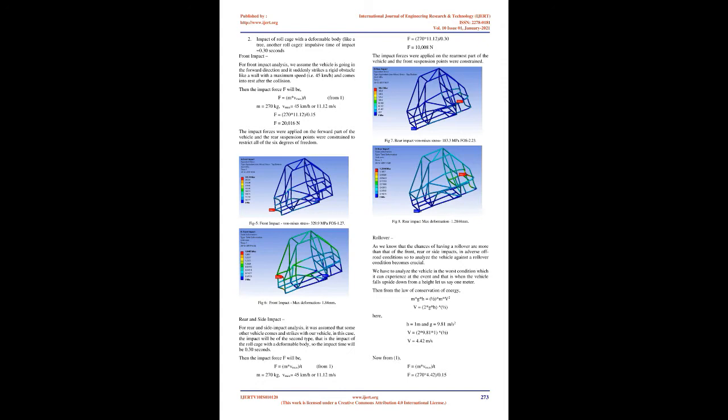Second moment of area, I, 13,478.64 mm4. Distance from central axis, C, 12.7 mm. Calculated bending strength, 444.497 MPa. Calculated bending stiffness, 2763.121 Nm2. We can see that bending strength and bending stiffness is exceeding the minimum required value, i.e.